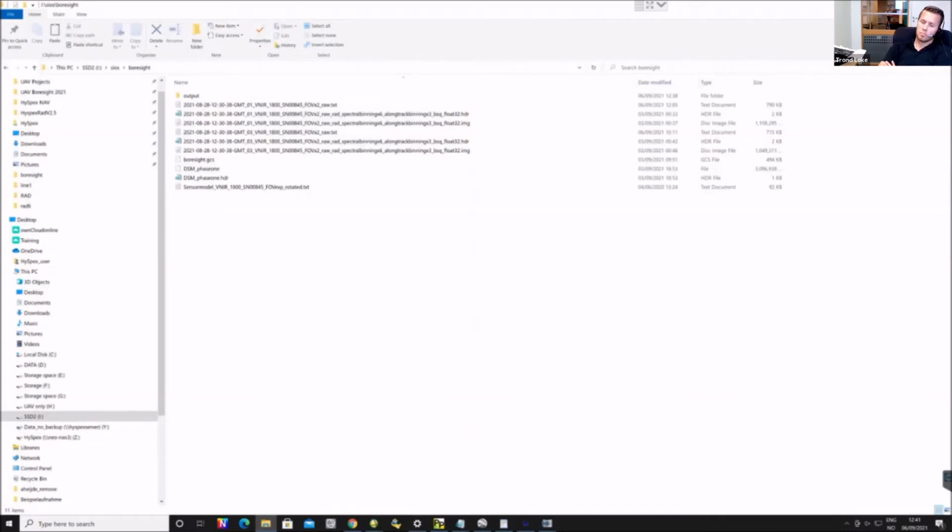If you're in the beginning of a campaign, you can use that to do the Boresight, because you don't care so much about your signal to noise ratio in your Boresight images. That's just to carry what you need to fly, right? So that's just to find the offsets. So yeah, the first day after installation is always Boresight, and that can be done in almost any weather. I would avoid heavy rain, but except for that, you can fly a Boresight.